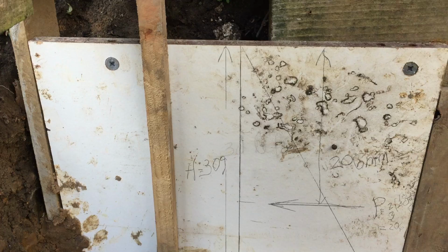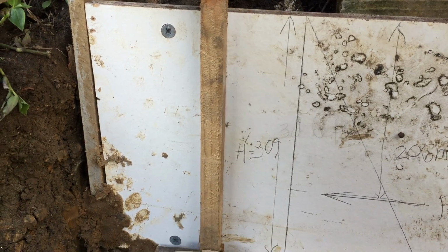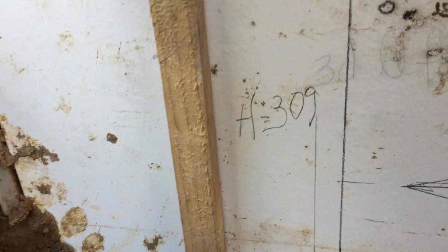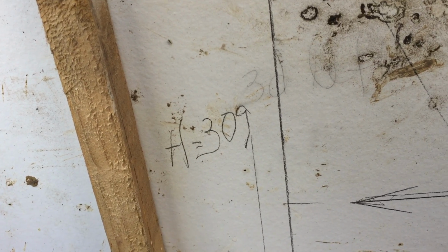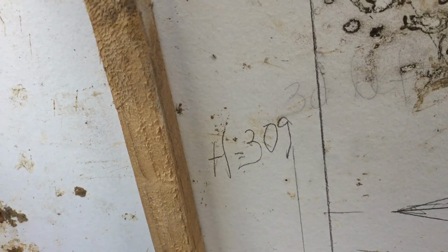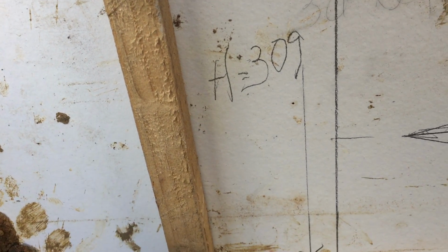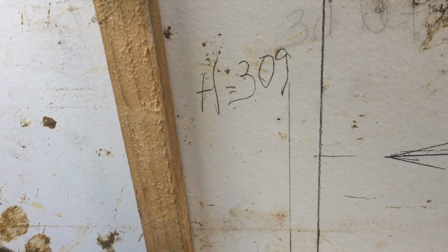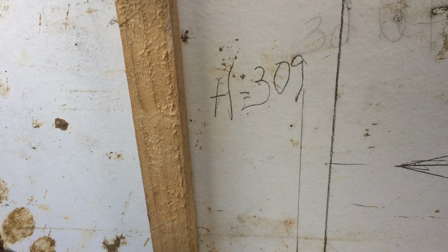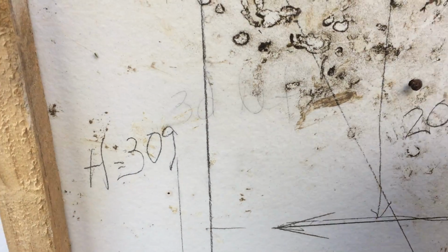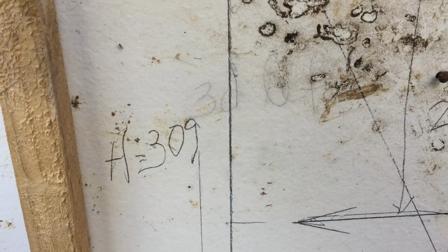That's the weight pushing this timber board, so I put these nails in here to resist the pressure of the concrete on this timber.